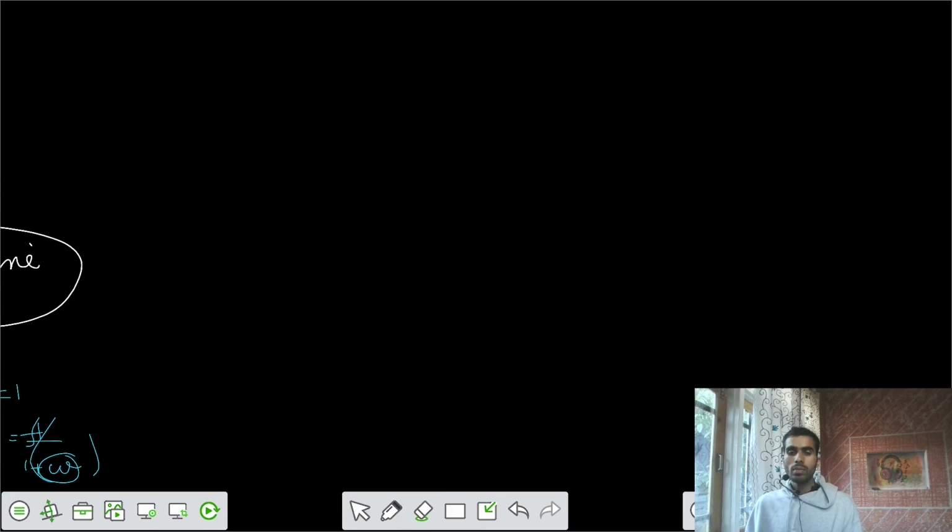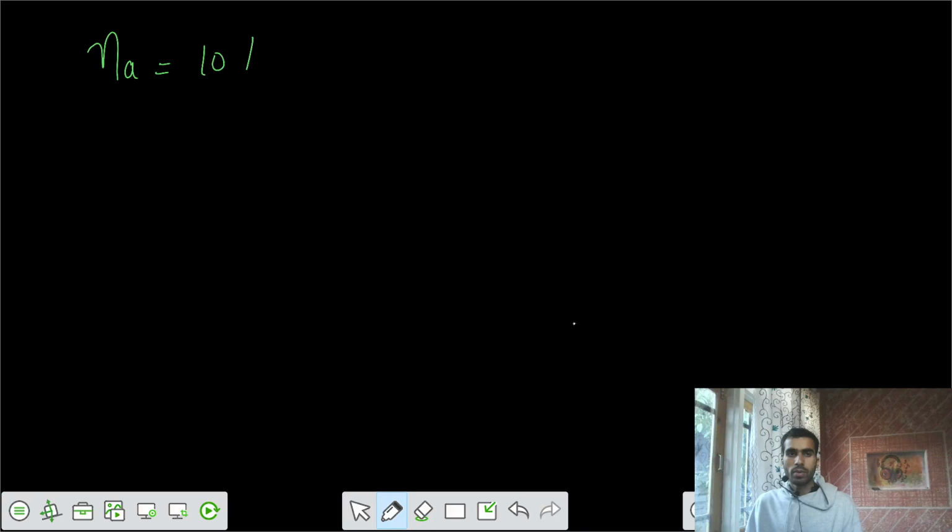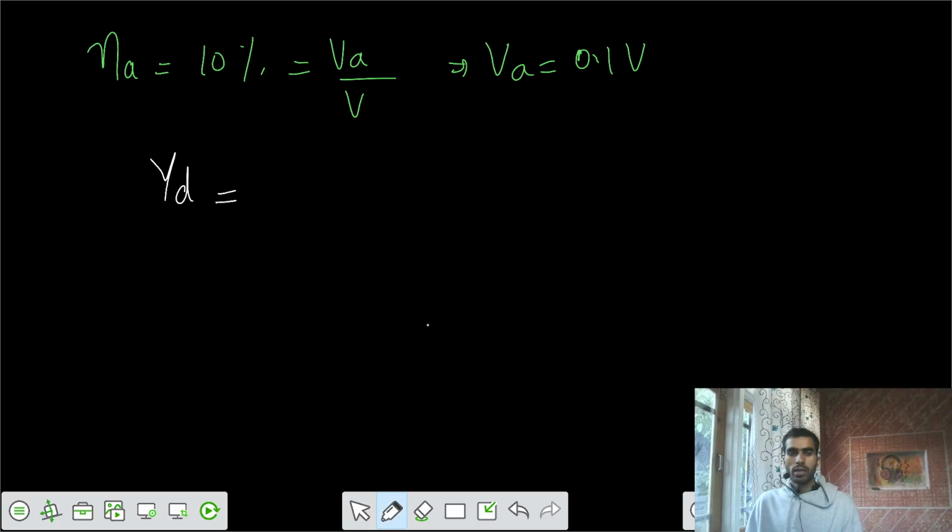Now let's say that your value of Na is 10%. That means the volume of air by total volume is 10%, that is, 0.1 times the volume of total soil. At that time, can you tell me what gamma dry we get? That is 1 minus Na, times G gamma W over 1 plus Wg.